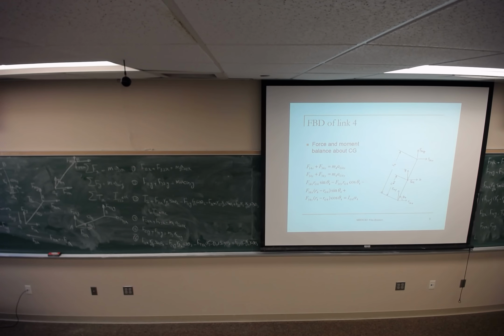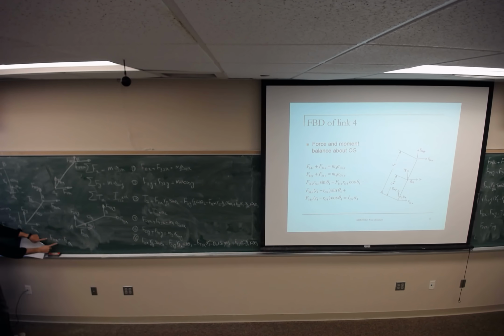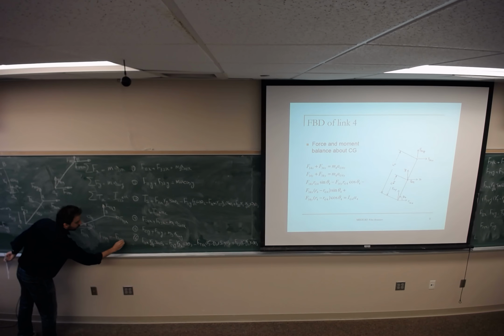I can solve for 9 equations. You might say that we didn't count F34y. As you see, we don't have F34y; we have F43y. If you remember, we talked about action and reaction. F12 equals negative F21. So if you have F34x, it's gonna be negative F43x.